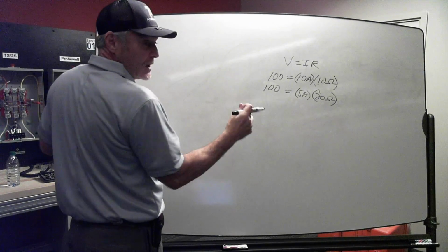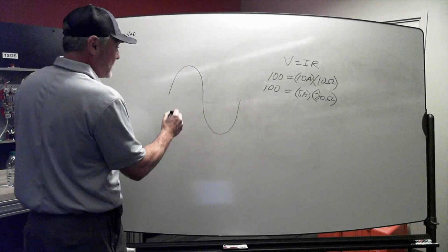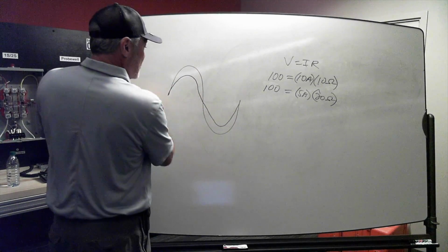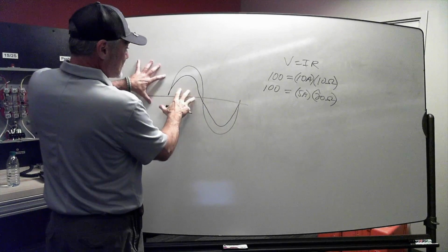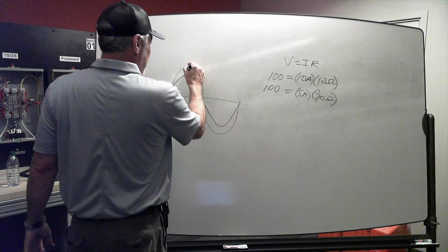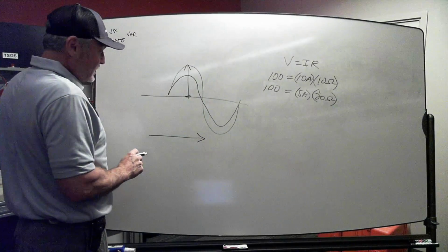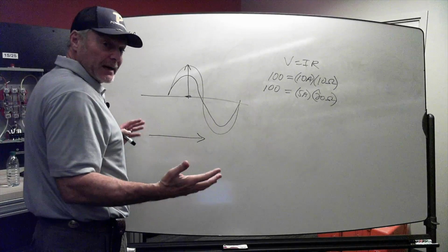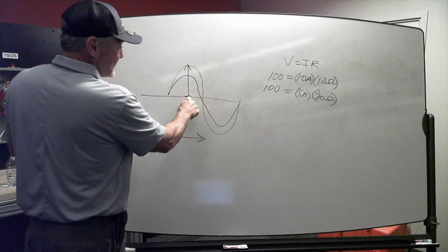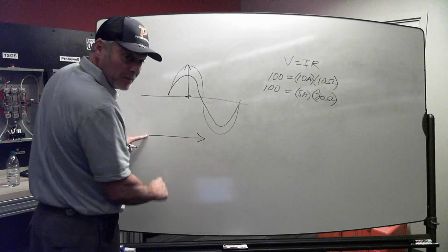So just so we're sure on something, because I get asked this out in the field. We were showing that wave out there, and we were showing them right there in sync with one another, right? Well, here's the thing. If you think about it, we're taking these sine waves and converting them to those vectors that you and I use. This amplitude from here to here is represented the same in a vector, okay? So what's so important to us, we've talked about this before, is that the length of the vector is the amplitude. The amplitude on the wave is the height from my axis up to here. Well, that equates directly to the length of my vector when I'm looking on my test kit.